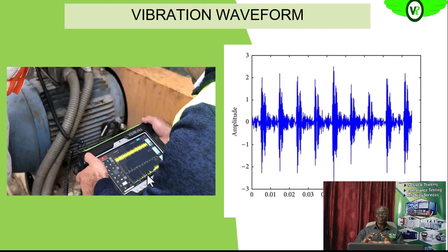If the bearing is cocked on the rotor or is loose on the rotor, all of this information you will see on different frequencies of the spectrum.